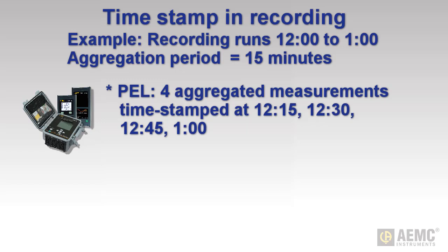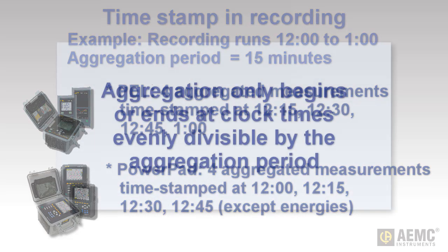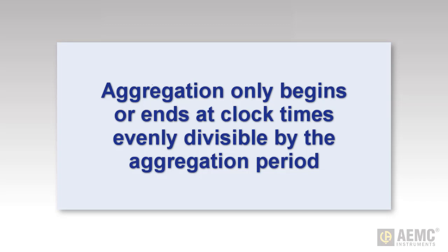On a PowerPad with the same configuration, most aggregated measurements will be timestamped at 12 o'clock, 12:15, and so on, with the final measurement at 12:45. The one exception is energy measurements, which in PowerPad recordings are timestamped at the end of the aggregation period, similar to PEL instruments.